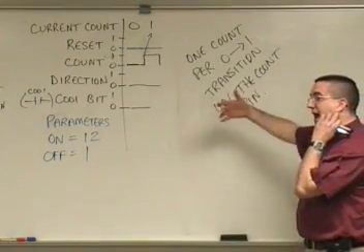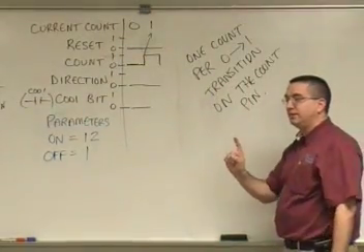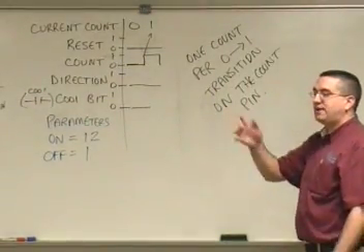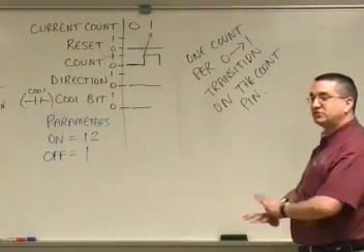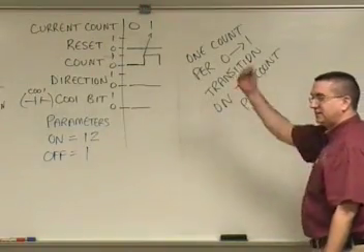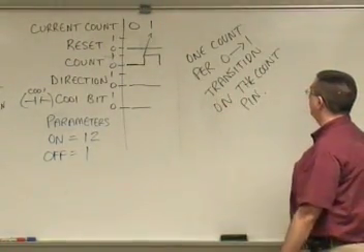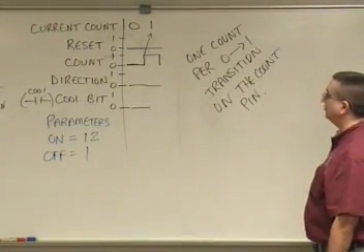So if I leave it high, it's just going to stay at that incremented count by 1. If I was at 2 and I went to high, it would go to 3. And if I left that switch on forever, it would just stay at 3. It's going to take a pulsating signal for it to change. One count per 0 to 1 transition on the count pin.